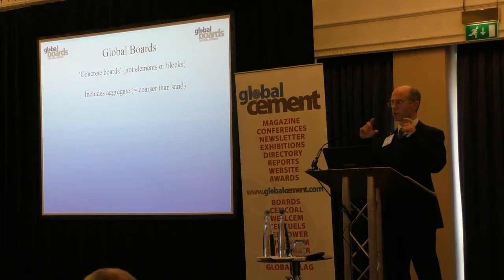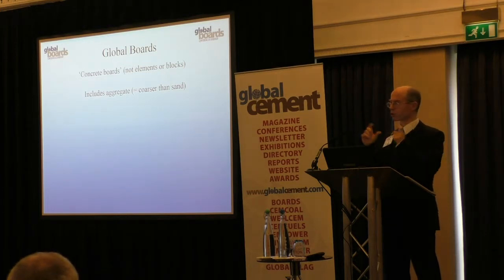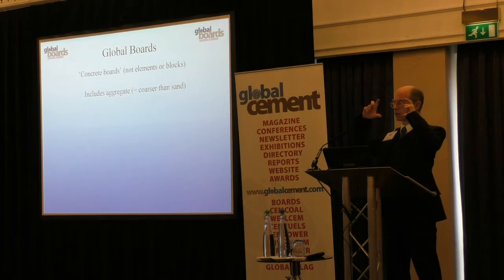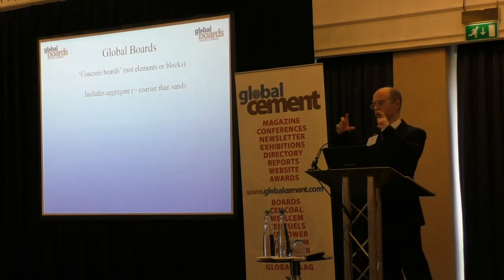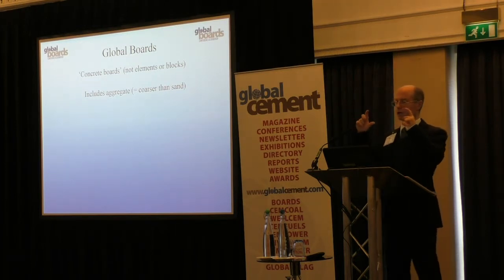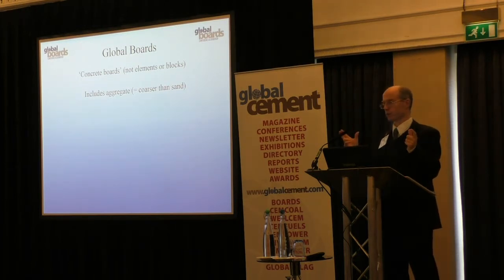And from a concrete perspective, you would have your basic cement, and this is where the American and the rest of the world might slightly disagree on some of these terms. You'd have your basic cement. If you would add sand into that and some other additives, that would make it into a mortar, and if it didn't have the water in it, it would be a dry mix. Put the water in, it's a mortar. You can use that for some applications.